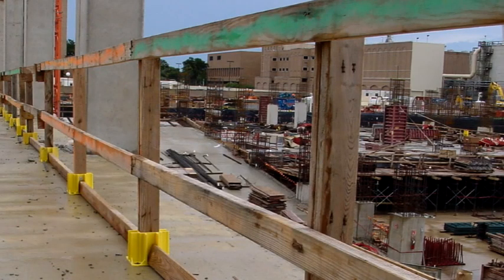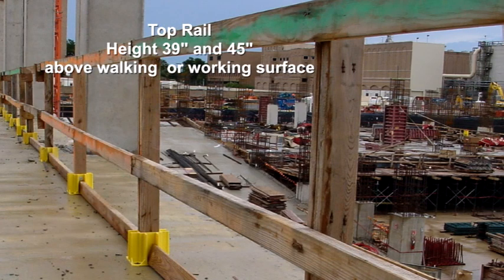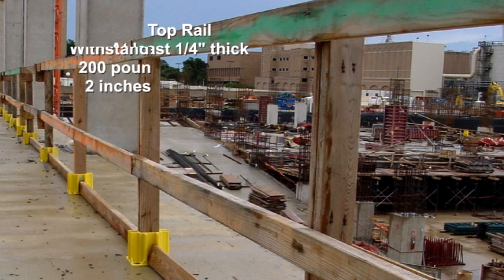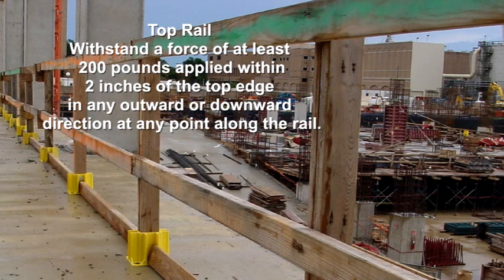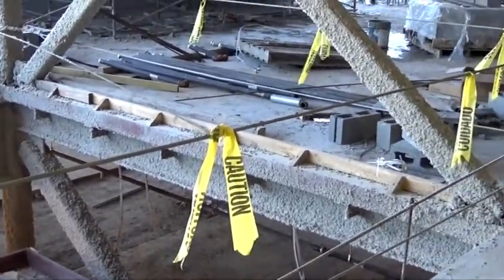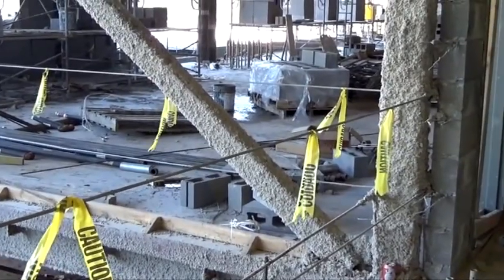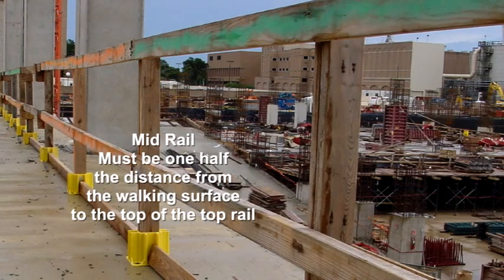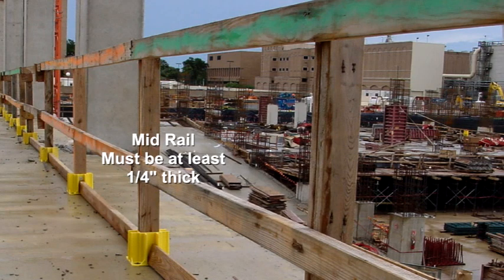OSHA requirements for guardrails state the top rail must be between 39 and 45 inches above the walking or working surface, be at least 1/4 inch thick, and be able to withstand a force of at least 200 pounds applied within 2 inches of the top edge in any outward or downward direction at any point along the rail. When using cable as a top rail, it must be flagged at not more than 6 feet intervals with high visibility material. The mid-rail must be 1/2 the distance from the walking surface to the top of the top rail and be at least 1/4 inch thick.